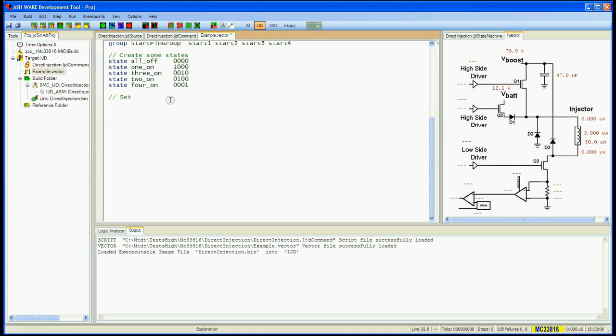The next needed command is the frequency command. This command establishes a master clock for the vector file. The units are megahertz, and this is typically left at 1 megahertz because this results in a 1 microsecond clock period, which I find to be intuitive and easy to remember. Plus, I am an expert at both multiplication and division by 1.